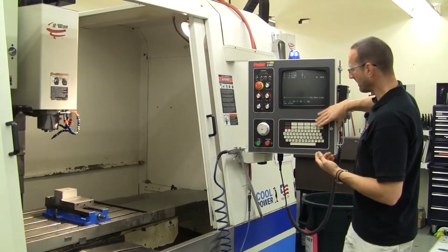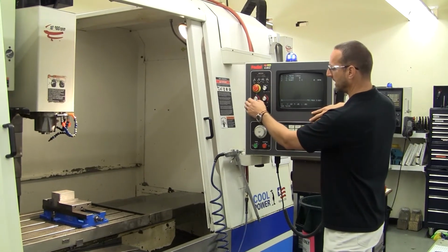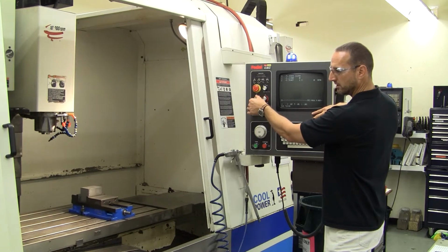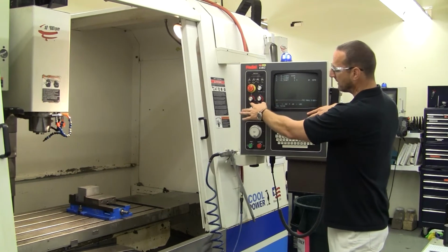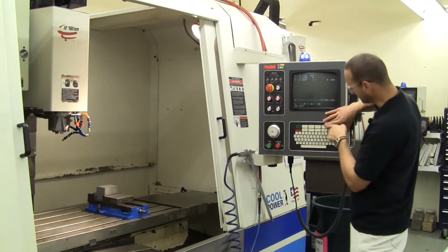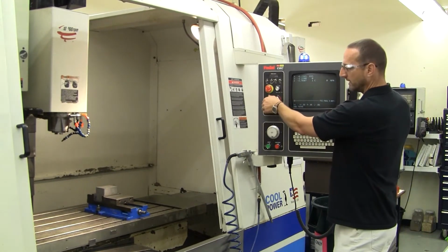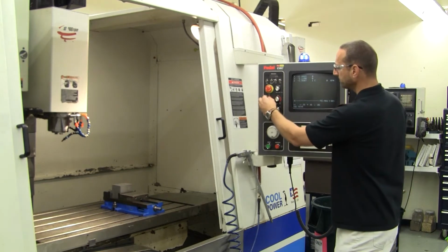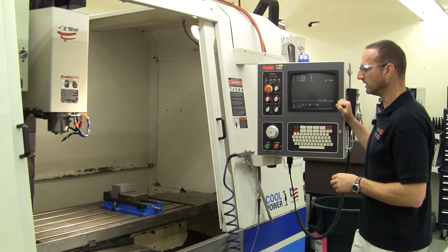So again, if I push the continuous jog button and hold it down and then dial down the feed rate override, you'll notice that the rate the table moves slows, actually to the point of stopping when I take it all the way to the bottom. And I'm still pushing and holding the jog key right now. And I can dial it back up and change it like so. So that guy is always active, and that is sometimes useful in jog mode